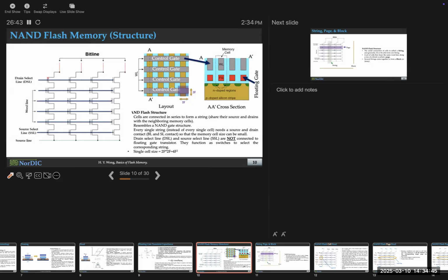There is an approach where we put all these flash memories in series with each other in every column. Okay, so in a column, they're literally physically connected. So this is a symbol of flash memory cell. Notice there is a difference between these two transistors. Do you see that? Is that visible? The top level and the bottom level are regular transistor, not flash. And simply because there are 4 doesn't mean there will be 4. There could be 16, there could be 64, there could be more. Okay, this is just a representation. But there will be a chain of flash memories, all connected in series with each other, like a NAND gate. That's why it's a NAND flash memory.